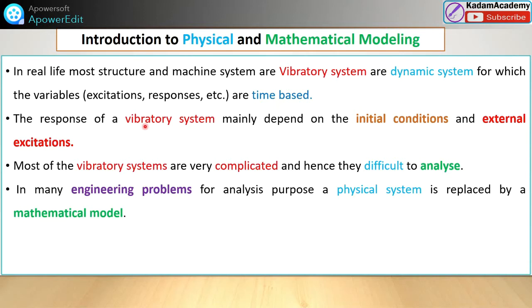When there is an infinite degree of freedom, that will be a continuous system, or we can say a distributed system with complicated differential equations, and we have to replace those complicated equations with simple equations with solutions. These differential equations become accurate and we can solve and analyze the continuous system, which is difficult to analyze, and hence they are generally analyzed by converting them into a discrete or lumped parameter system.